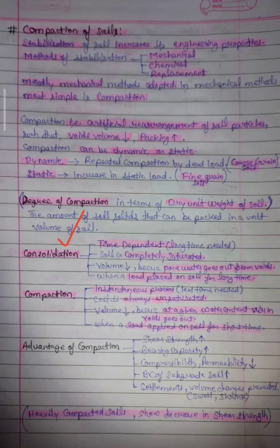Now consolidation is a time dependent process. It takes a long time. In consolidation, soil is completely saturated. In consolidation, volume decreases because pore water goes out from voids. When a load is placed on soil for a long time, consolidation happens over a long period of time.